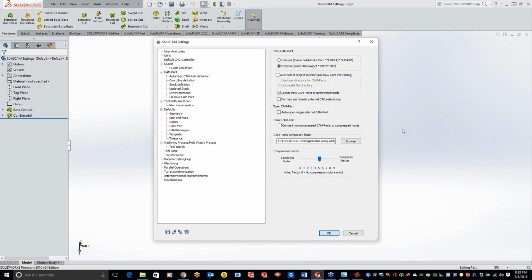Now, I was telling you guys you can save all these different areas onto the server except for one. This is the one that you do not want to change. And I really want to emphasize, do not move this to a different location. Keep this where the default location is. If it's in a different location, we're going to get a lot of lag going on with saving. We might get some crashing going on because of permission issues. So please, please, please definitely keep this in the default location.